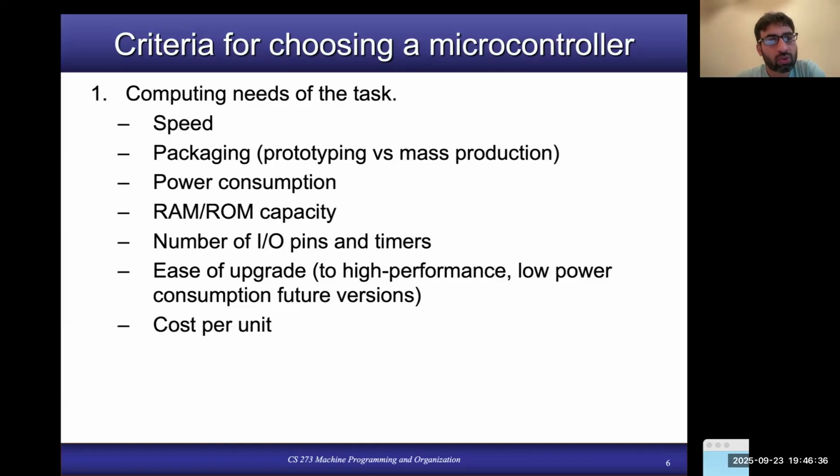Also, power consumption. We don't want to design a product which actually consumes too much power, because most of the time microcontrollers are used in systems which are battery backed and limited on power. So we want a microcontroller which consumes relatively lower power.